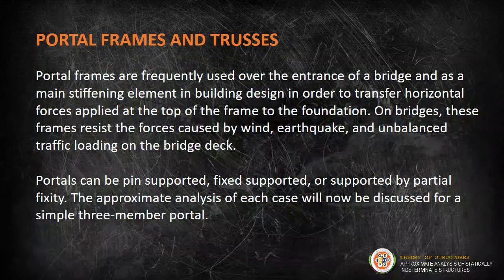Portal frames and trusses. Portal frames are frequently used over the entrance of a bridge and as a main stiffening element in building design in order to transfer horizontal forces applied at the top of the frame to the foundation. On bridges, these frames resist the forces caused by wind, earthquake, and unbalanced traffic loading on the bridge deck. Portals can be pin-supported, fixed-supported, or supported by partial fixity. The approximate analysis of each case will now be discussed for a simple three-member portal.